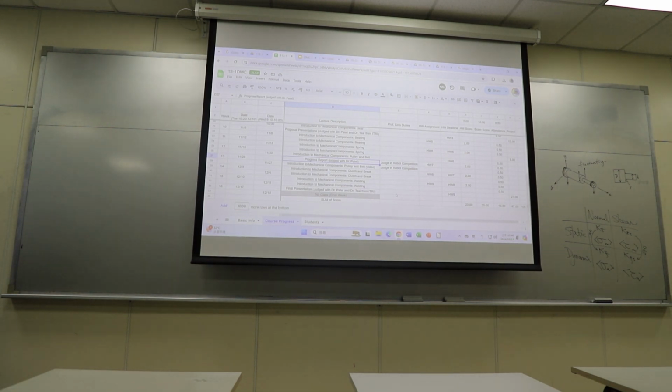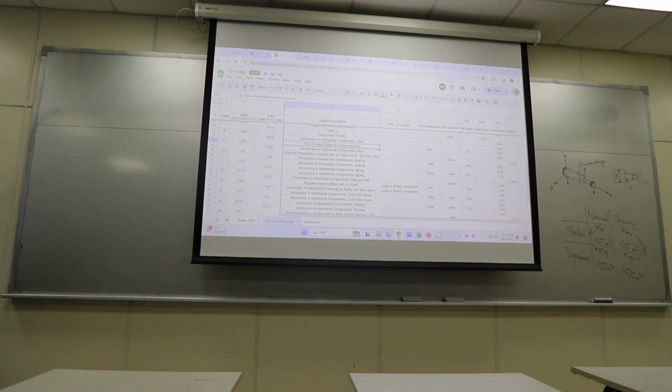You can try to analyze by hand, by computer, or you can use the software that we introduced, ANSYS. In order to use ANSYS, you need to make CAD designs and put them into the software. It will analyze the stress distribution for you, basically telling you the von Mises stress, and you can even use it to compute the safety factor.